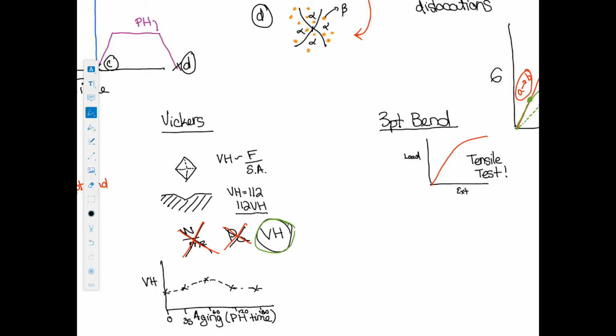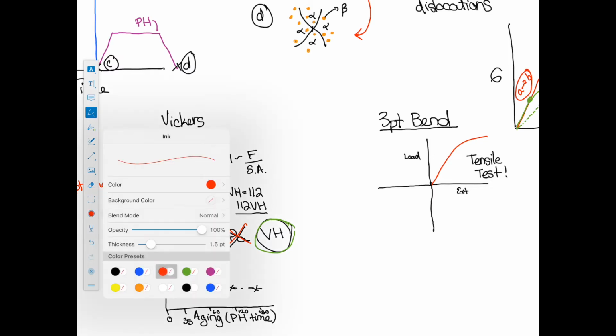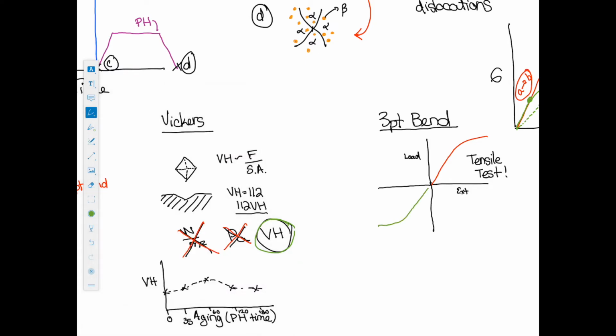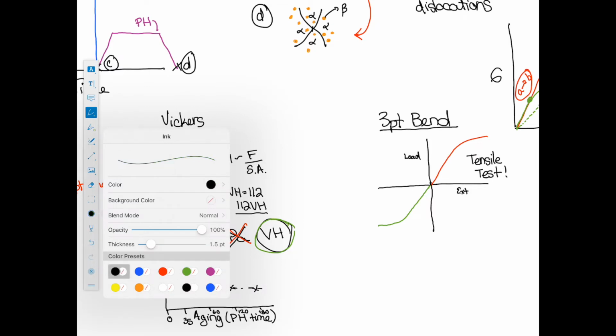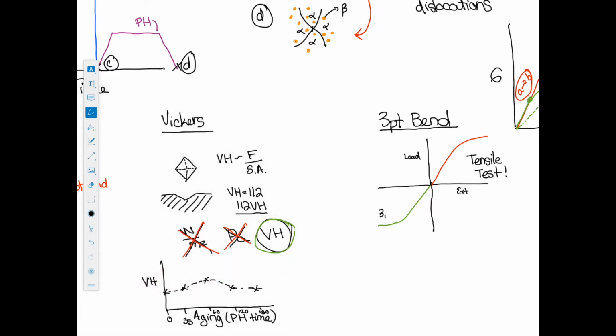The 3-point bend test is a compression method on the Instron machine. So the way that your data is going to plot is if you take the data that I've given you, it will plot in the bottom left quadrant instead of the top right quadrant. And this is for a 3-point bend test. And so it's okay. That's completely fine.